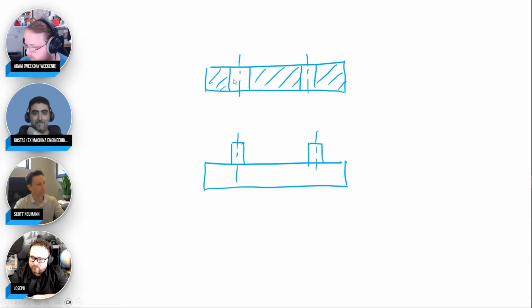How do I make sure that these holes will not be off position too much where they accept the pins? And it's real easy. Smallest hole, biggest pin. And then when you do your position tolerances, the tolerance zone always applies the length of the feature. So you get a cylindrical tolerance zone on this one, you get a cylindrical tolerance zone on this one. Now, when you insert that pin into the hole, the tolerance zones overlap each other. So it's just a really easy smallest hole, biggest pin, split it between the parts.